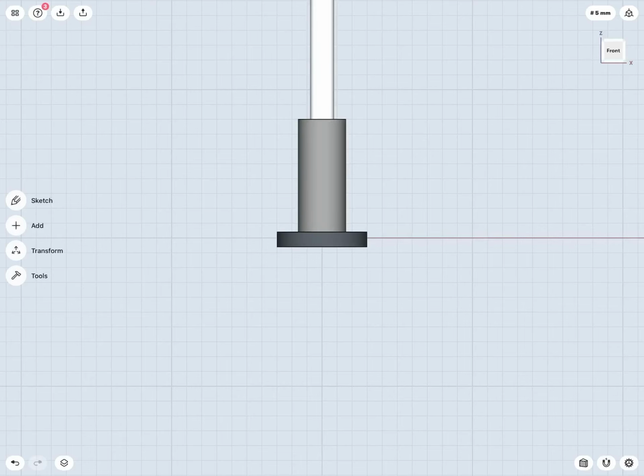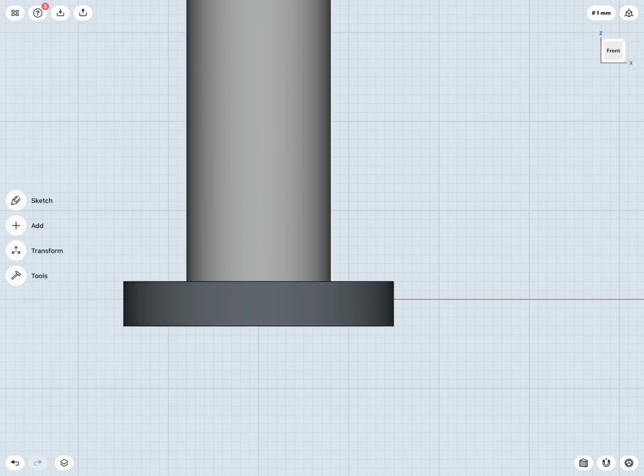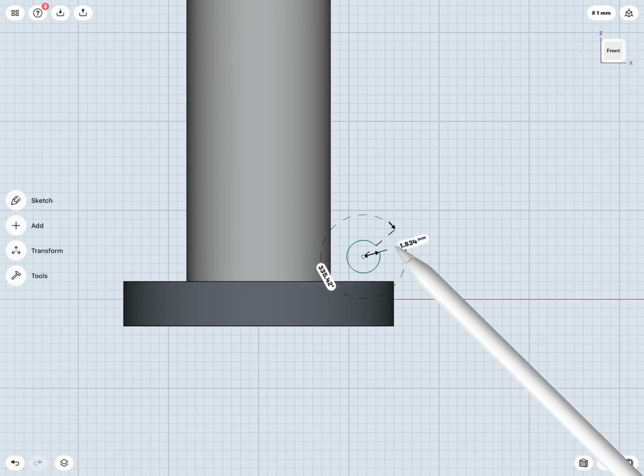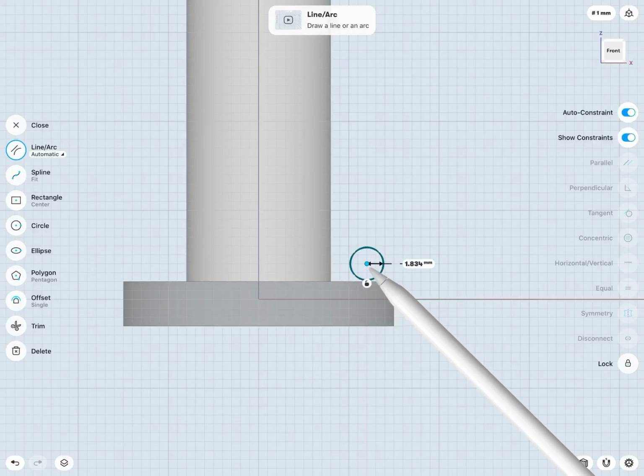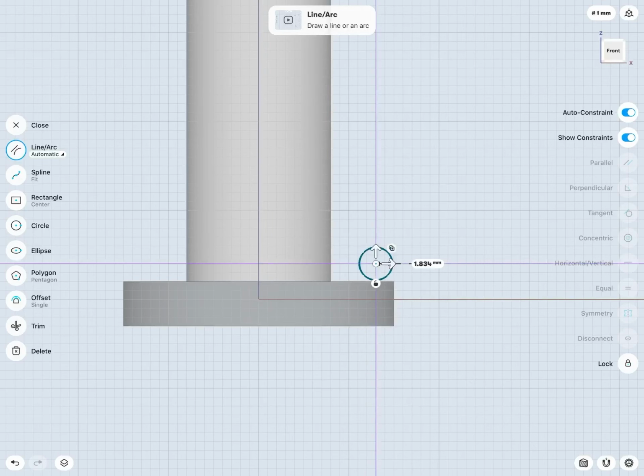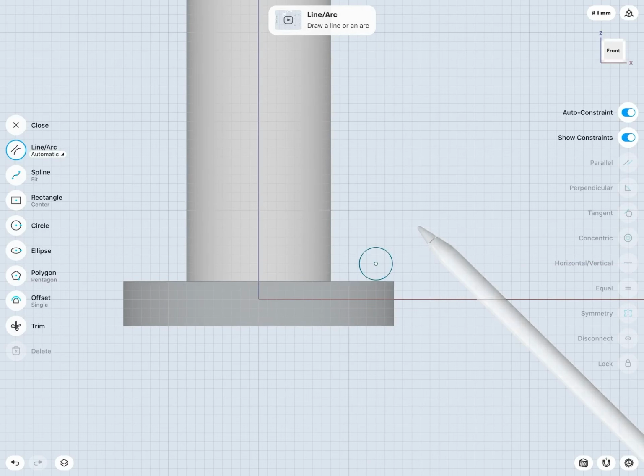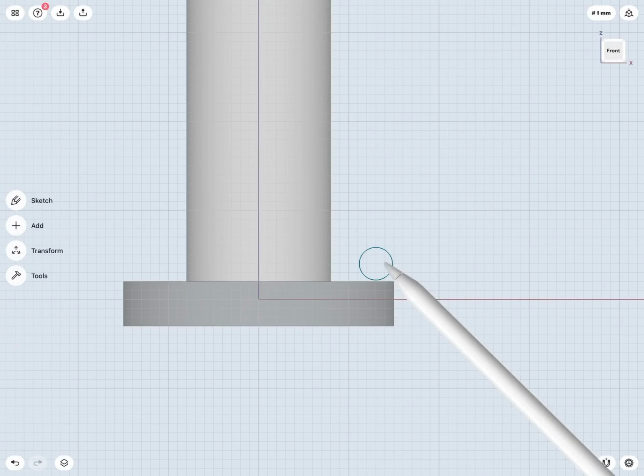So, for example, to recreate this spring, first just jump to a front view here, and draw the profile I'd like to revolve. In this case, it would just be a simple circle, maybe something like this. And I can fine-tune the locations or dimensions as needed, but I'm not too worried about them here, so I'll just throw in something like that there. And then really all I'm doing is revolving this circle about my z-axis.